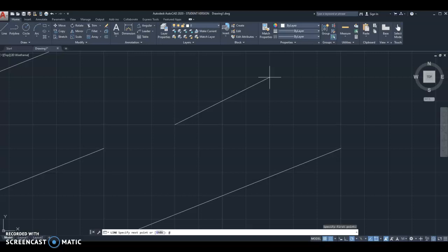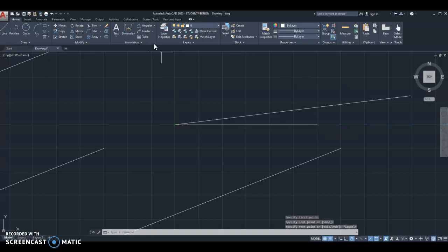I need to specify the length of the line. I'm going to say 5. And then instead of a comma, I'm going to hit the shift comma, which gives me that symbol there that looks kind of like a less than symbol to indicate the angle, and I can say 7. So 5 inches long at a 7-degree angle. That gives me exactly a 7-degree angle.